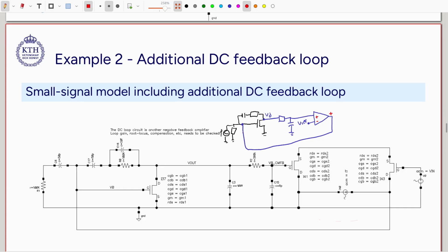It is going back on the feedback plus. The single stage transistor connected as a common source will invert this signal at the output. So the transimpedance is an inverting amplifier. It will put minus. The filter will not change the sign, so this is still minus. So we have negative feedback, minus coming to plus. Okay, so that is the correct connection.